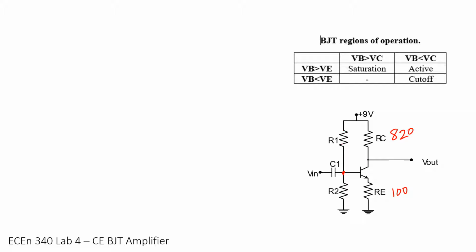Okay, so we've got a voltage divider here. We need to have a voltage here so that this transistor turns on, and we are controlling this current. So we want to have the appropriate amount of current through this resistor to get this voltage where we need to be, which is in between our rails. So step one is we should think about our rails.